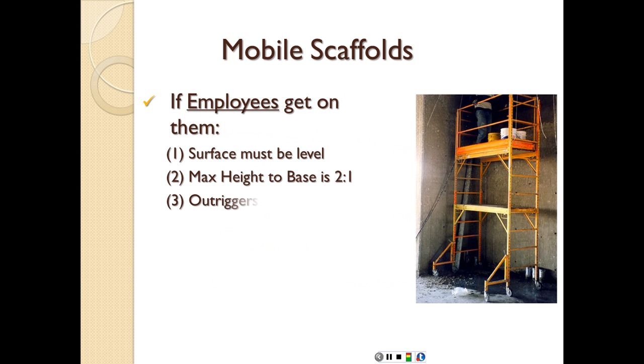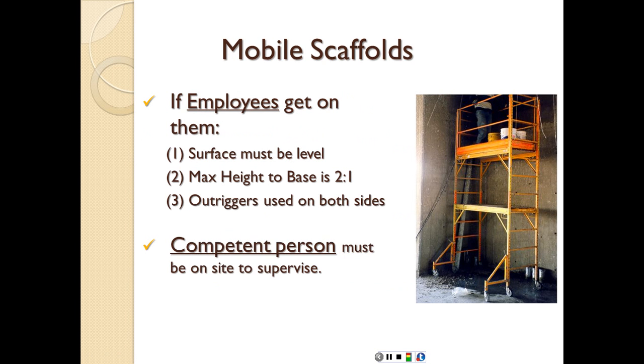From time to time and for certain kinds of work, we're going to have mobile scaffolds for painting, for example, and similar other work. So here you can see the worker. It has the guardrails and the mid-rail. It might have a toe board as well to prevent falling debris. It has the ladder type access on both sides. It's properly fully planked on both working surfaces. It has some braces here. It has the casters at the bottom, and it has outriggers to increase the width of the base of the